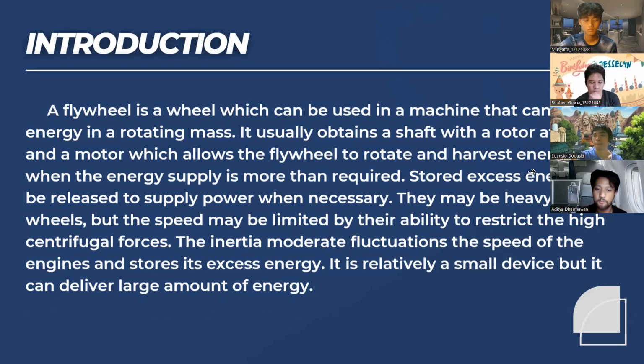The flywheel itself can be a heavy metal wheel, but the speed may be limited by its ability to resist high centrifugal forces. The inertia moderates fluctuations in the speed of the engine and stores excess energy. The flywheel itself is a relatively small device, but it can deliver large amounts of energy depending on how it is manufactured or how it is used.